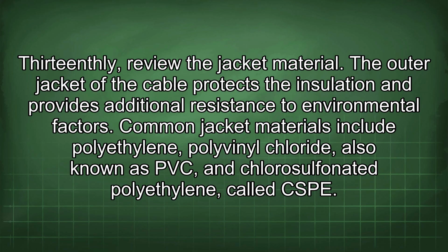13thly, review the jacket material. The outer jacket of the cable protects the insulation and provides additional resistance to environmental factors. Common jacket materials include polyethylene, polyvinyl chloride, also known as PVC, and chlorosulfonated polyethylene, called CSP.